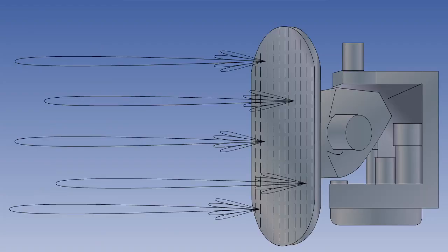A much smaller type of radar antenna is the flat plate or slotted planar array. We have seen with the ILS localizer antenna that if a series of antennae are spaced at half a wavelength and are fed in phase, the energy from the antennae is enhanced. This is the principle of the slotted array antenna, and the energy is emitted from the multiple slots in the plate. This type has the advantage that the side lobes are smaller, thereby wasting less power. The RF energy is therefore concentrated into a narrower beam. It therefore needs less electrical power. This makes it a popular choice for airborne weather radars.